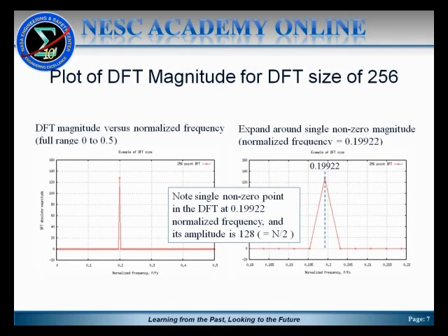And you might recall from part 1 of this presentation that the discrete Fourier transform coefficients are scaled by N, or N over 2 for the end points of the frequency of the discrete Fourier transform. That is at a normalized frequency of 0 and a normalized frequency of 0.5, which occurs for k equals 0 and k equals N over 2 in the summation that we saw a couple of charts earlier. The scaling is the value of N, where N is the number of points. For all other points in between the endpoints, the scaling is N over 2.